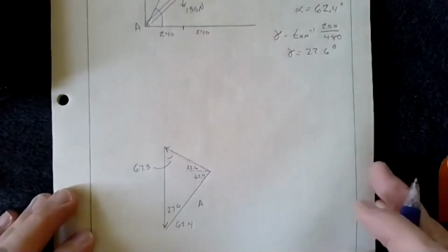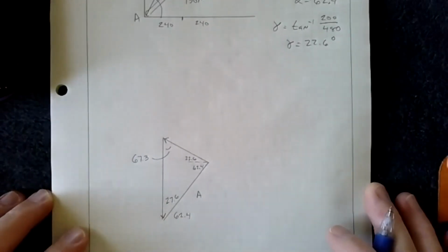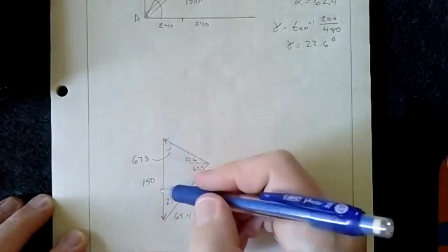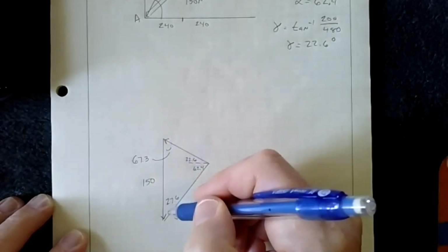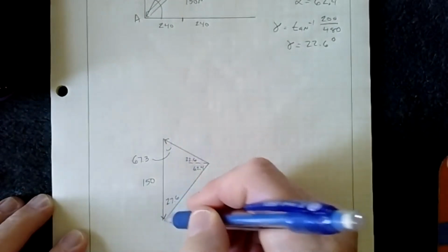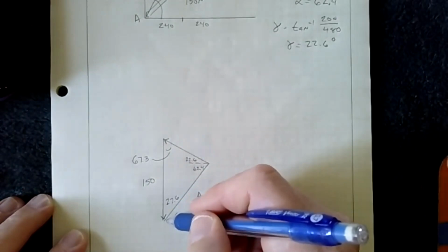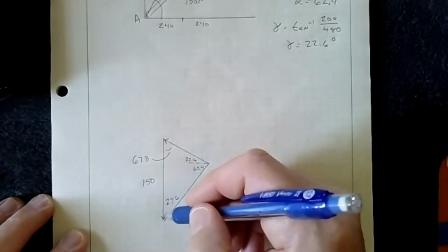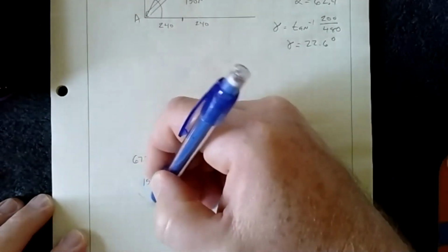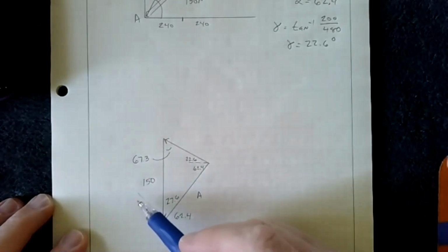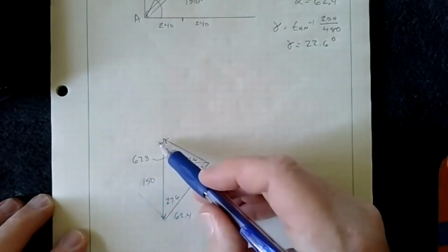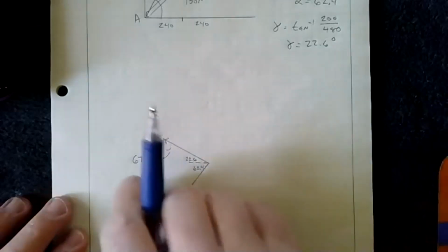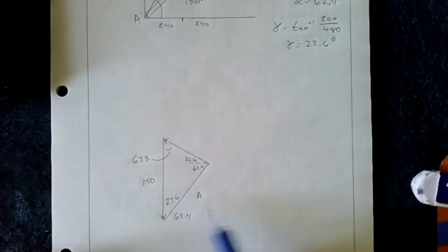So I've kind of moved it down here. What I've done to get the force triangle, first, as whenever you do a force triangle, you draw either the vertical or horizontal line. So I drew the vertical. I know that then that's going to have to connect to something. Now, at that point, I could have drawn this line here. So it could have come like that, and then I would have drawn this line up there. So it would have just been a mirror image. So it really doesn't matter how you connect it. Since I'm right-handed, it seems more logical to draw it this way.